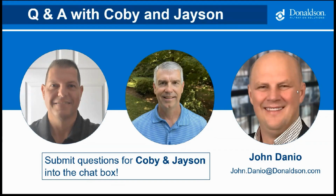Thank you. And next question, what are the major watch-outs if you need to install orifice disc for proper balance? So, I mean, that's just another way. Instead of using a blast gate, someone might put an orifice there to add some restriction in a line so that you're balancing the system somewhere else. Putting that in the line obviously can create some restrictions where you're no longer getting the draw or the suction where you need it in that line. Sometimes those orifices, depending on how they are, can add some noise to the system as well. You get more of a whistling effect through there.